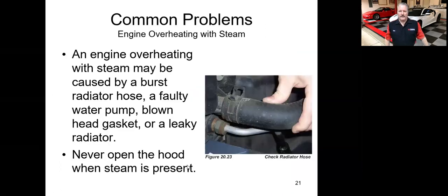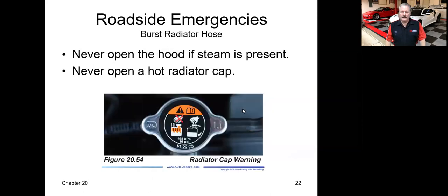Engine overheating with steam. You've got a lot of steam coming out from underneath your hood. Be careful about opening up the hood right away. You don't want to have a bunch of steam coming at your face, so you may just want to wait a little bit. Could be a hose, could be a cracked radiator, something like that.